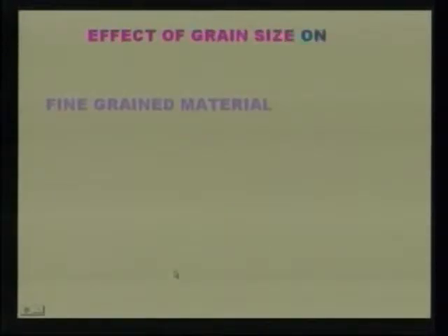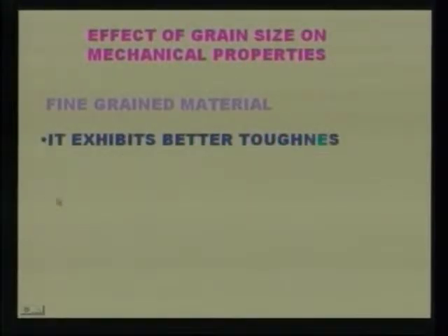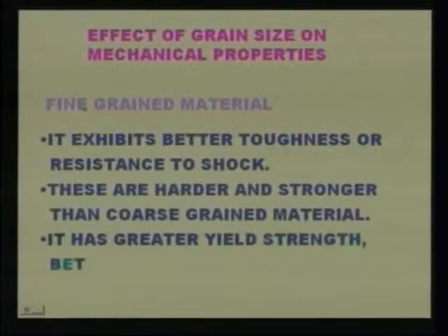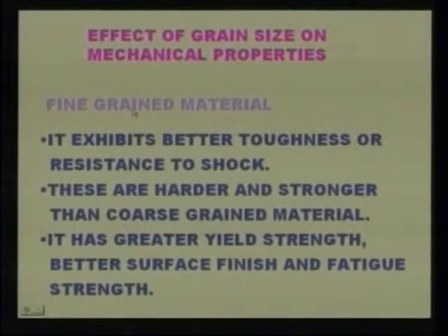Now let us see another effect, the effect of grain size on mechanical properties. In mechanical properties, let us discuss the fine grained material. In fine grained material, the effects are, it exhibits better toughness or resistance to shock. This is an advantage. These are harder and stronger than coarse grained material. It has greater yield strength, better surface finish and fatigue strength.